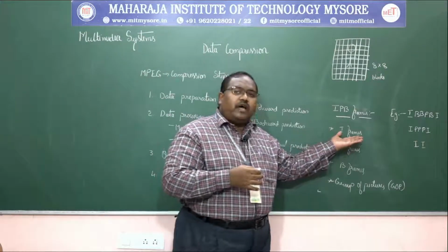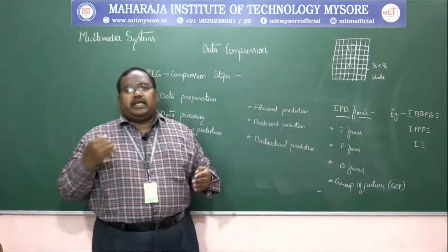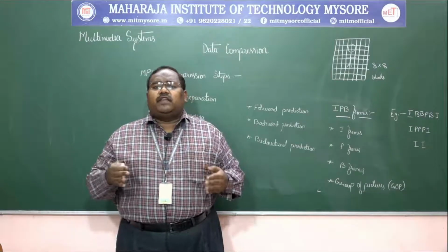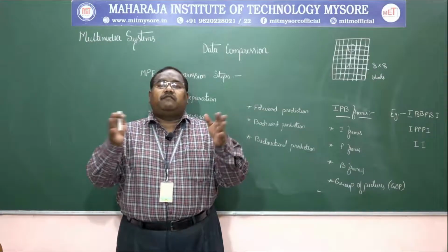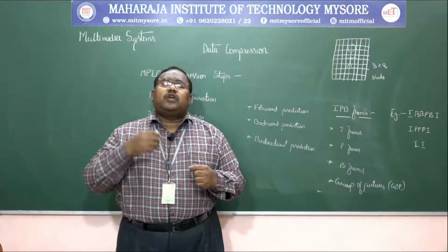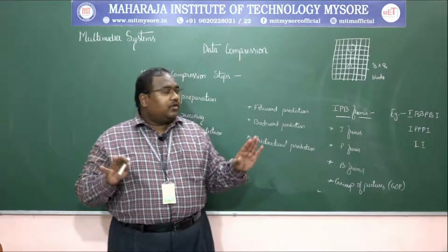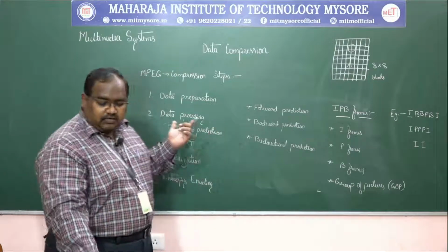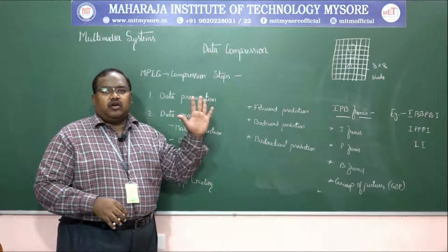Sometimes it consists of I frames, which are constant still images. So we retain that and try to exclude the high frequency component, the AC component, which consists of a very high frequency range. Our main aim here is to remove the high frequency, and by applying the DCT we achieve this by removing the AC component.